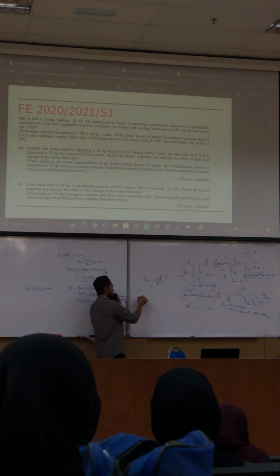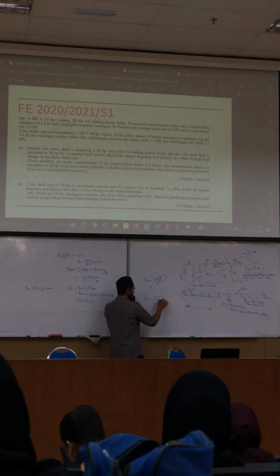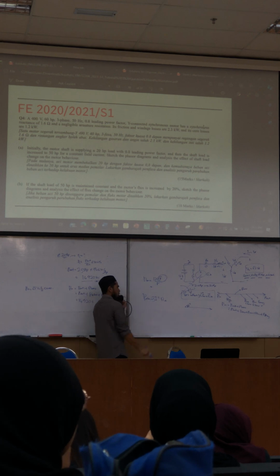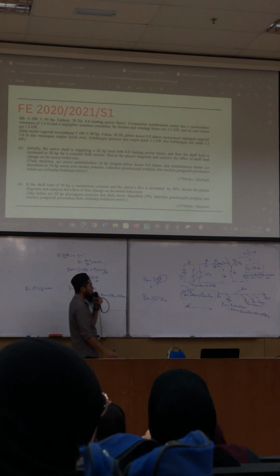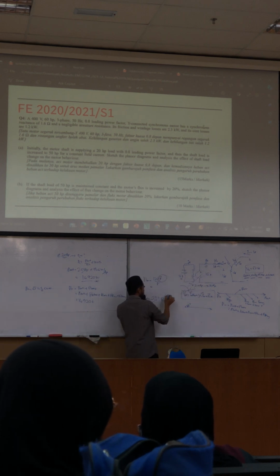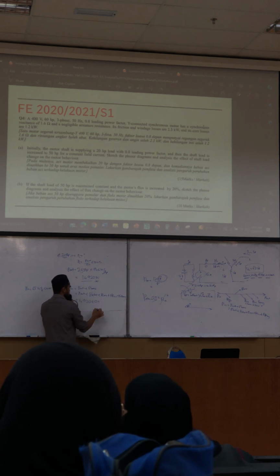Electrical losses equal to I square R times 3, the losses of your electrical component. But since we assumed RA is 0, P electrical is 0.